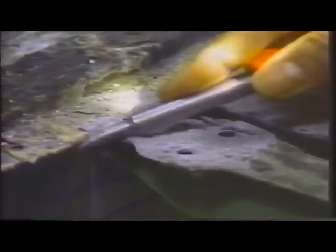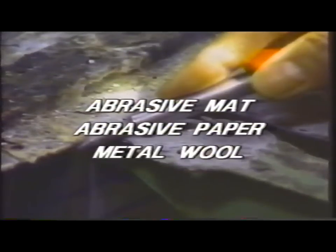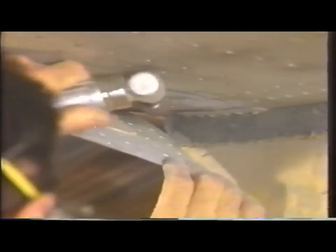The primary methods of corrosion removal used in the field are mechanical. Mechanical corrosion removal is done either by hand or with handheld power tools. Hand sanding uses abrasive mat, abrasive paper, or metal wool and is suitable for small areas. Powered mechanical sanding, grinding, and buffing use abrasive mats, grinding wheels, sanding discs, or abrasive rubber mats.